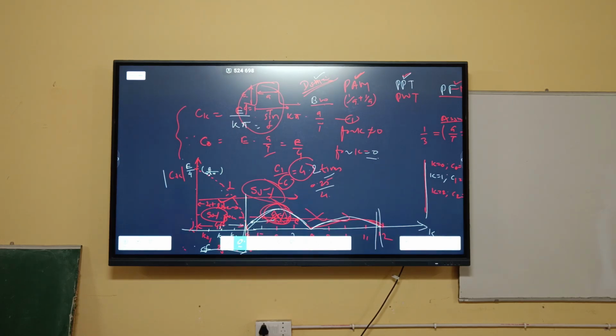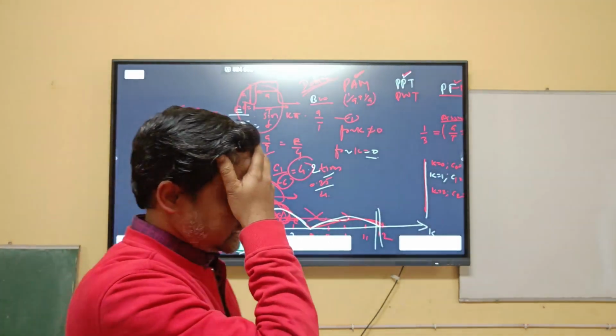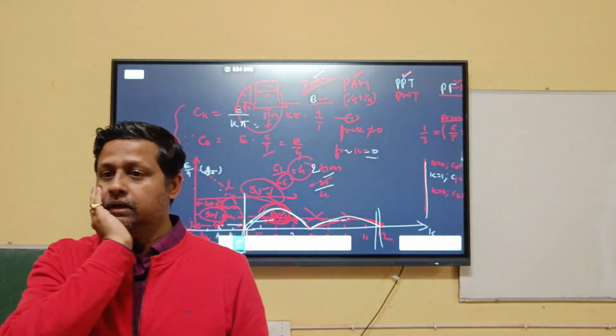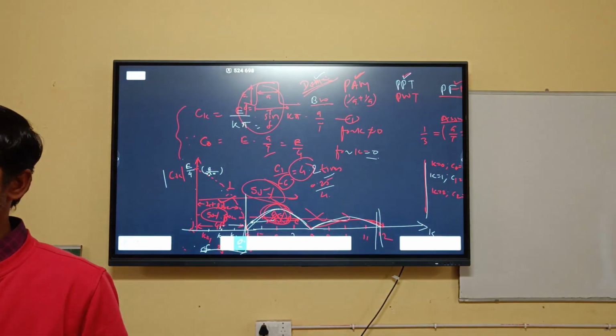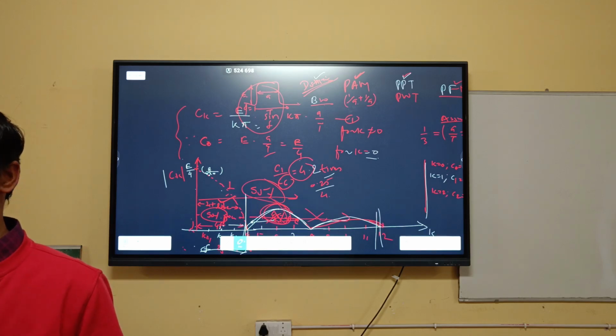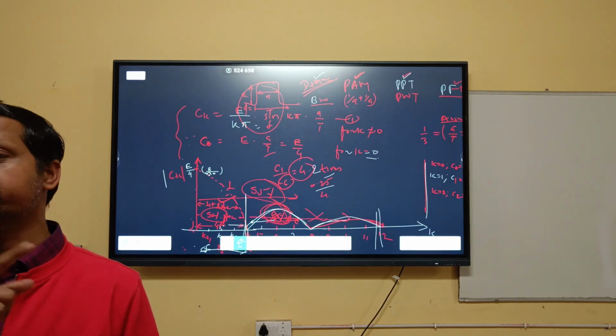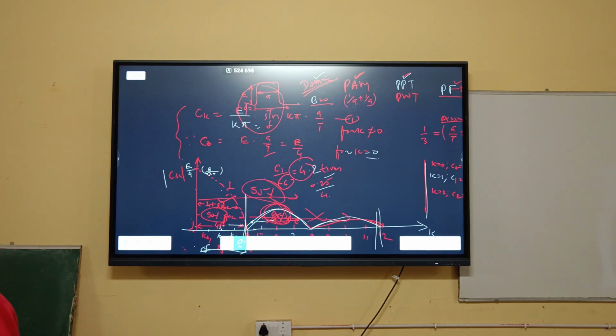The whole game is this, isn't it? So there you cannot afford to apply FM, because FM itself works on the principle of change in frequency. Understand? So in one case distortion is high, in another case bandwidth requirement is high, but it provides you a better signal to noise ratio. So if you have the flexibility, go for frequency modulation. If you have the flexibility, go for phase modulation. The most classical is always amplitude modulation.